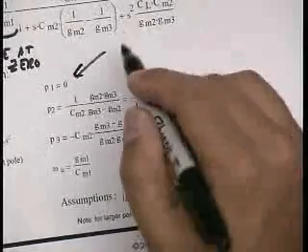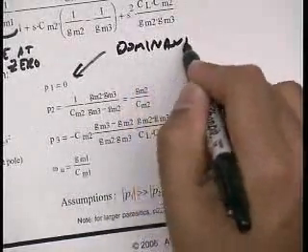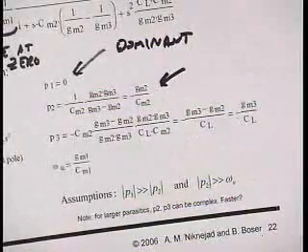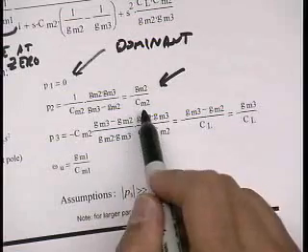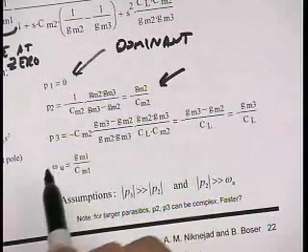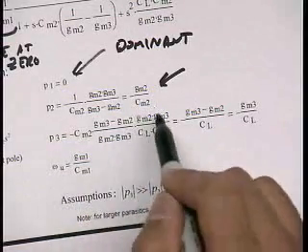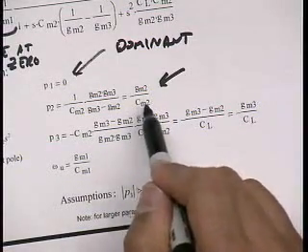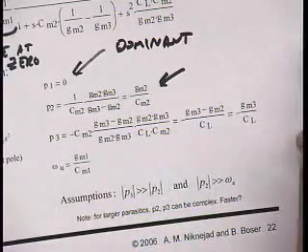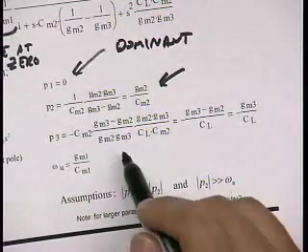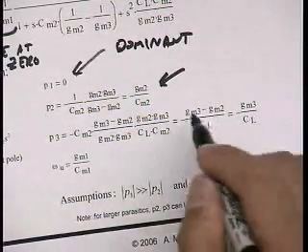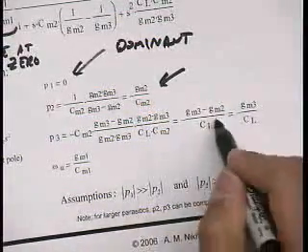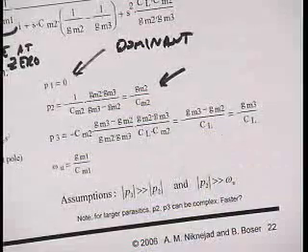That's the DC pole. That's the dominant pole. Of course, it's not at DC. The second pole looks like it's at a pretty high frequency of minus GM over CM2. Remember, CM2 is quite a large capacitance. So again, you have to be careful. This is not necessarily as high as you might think. And then the third pole, if we simplify it, is first of all the difference between GM3 and GM2, and determined also by the load capacitance.